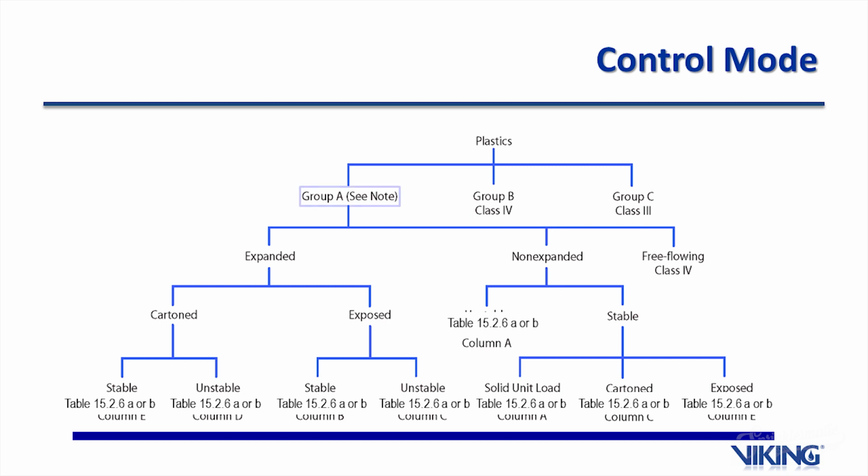But now I've got Group A plastic. What's the next decision? Is it expanded, unexpanded, or free-flowing? Okay, we covered those definitions. It's expanded in this case. Is it cartoned or is it exposed? Is it in a box or is it not, this expanded plastic? Okay, it's cartoned. Is the pile stable or is it unstable? Okay, it's stable.